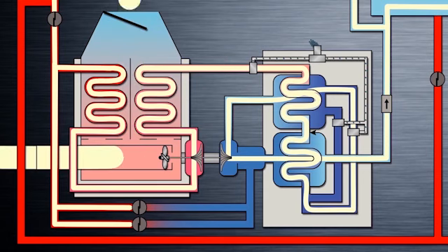Once the air has passed through all these stages, it has already been conditioned, cooled, and is now ready for distribution into the aircraft zones. From the packs to the main distribution, or mixed manifold, a valve opens to allow the conditioned air to flow in that direction. Air from the packs is delivered at one constant, fairly cold temperature.